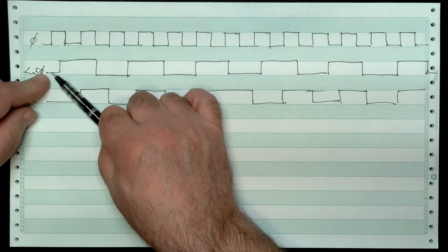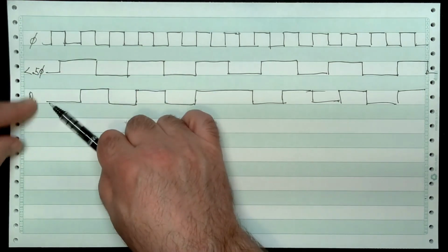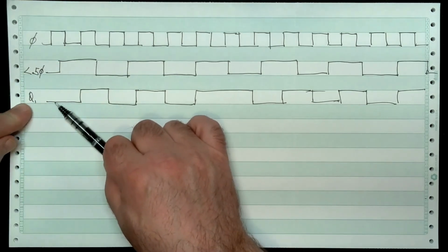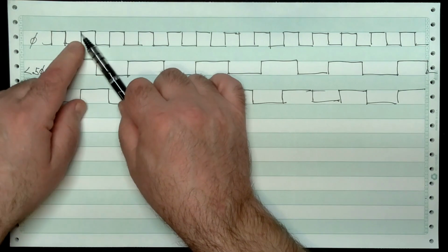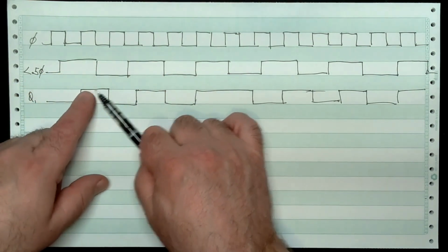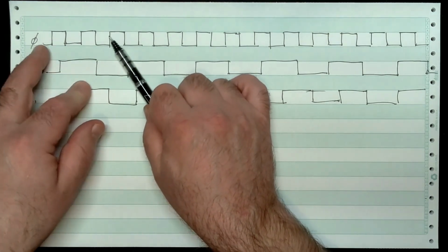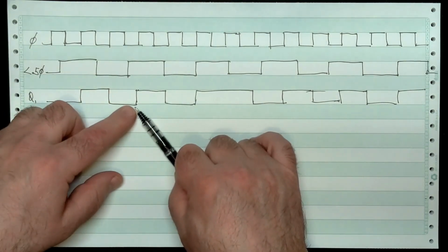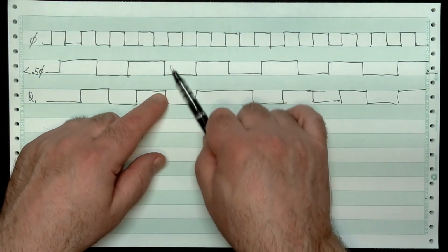the clock trigger input, which is what this guy is, is low. Therefore, the output of that latch, I marked as Q1 in the drawing, is low. The next time it looks is on this rising edge here. It sees a high. That then goes high here. Stays high. It's got another rising edge of phi. We see a low. It goes back down here. Rising edge here. It sees a high. It goes up. Rising edge here. It sees a low. It goes down.